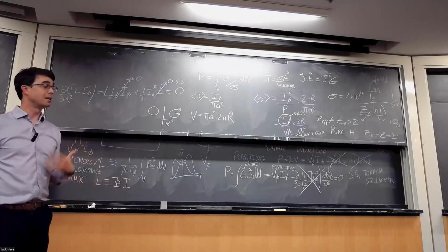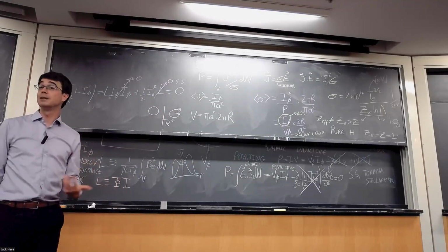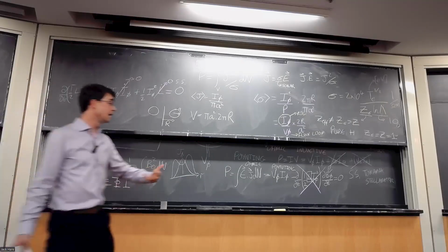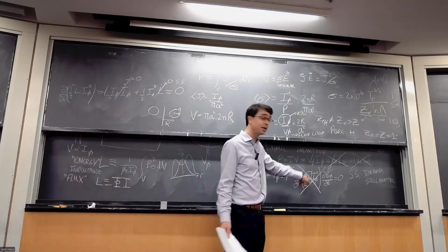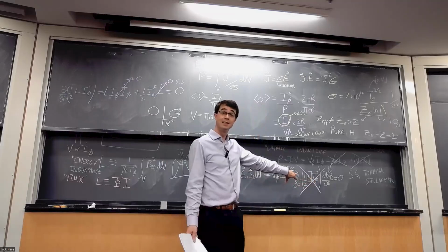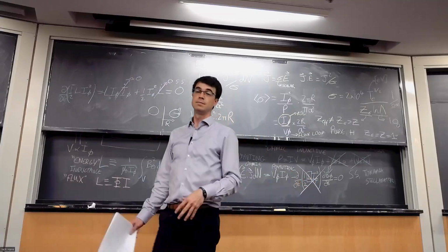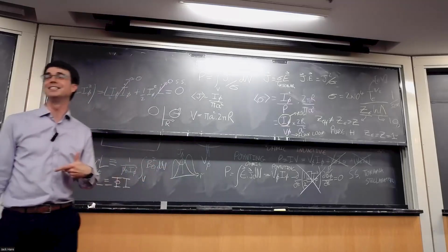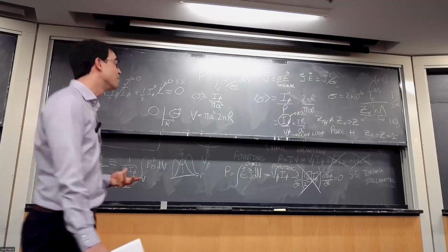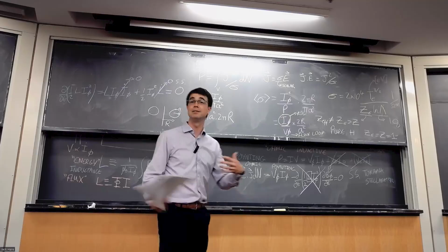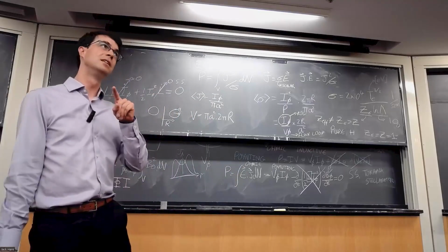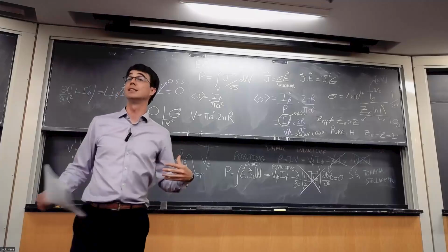We're talking about steady state, we're talking about times. So there should be some sort of time scale that we're measuring. There should be an inductive time scale here where we could form a time scale out of this. The current over the rate of change of the current will give you some time scale. So that would be a good time scale that needs to be small. It needs to be smaller than the pulse length.